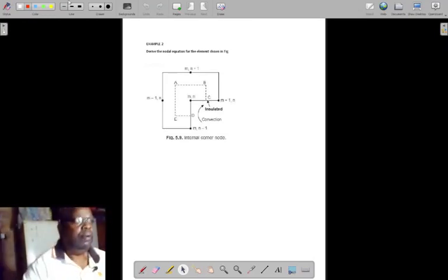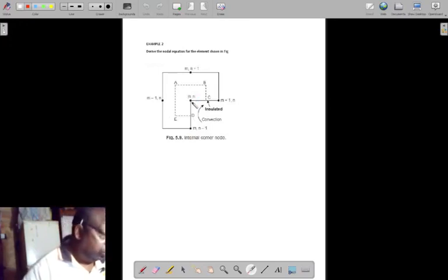So we have a node there that is in direct interaction with that node, a node there, a node there, and a node there. So we are after the temperature distribution around this node, and we have that surface being insulated, and there is a convective environment there.